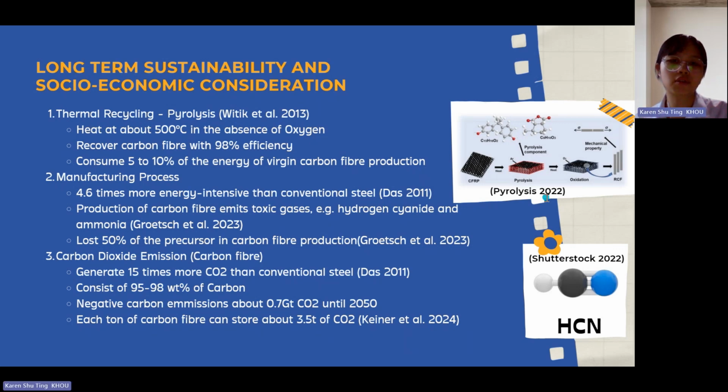First, in terms of long-term sustainability use, the material used should be recyclable. For your information, carbon fiber reinforced polymers are difficult to recycle due to their structure. It utilizes cross-linked thermoset polymers for their matrices. Here is one of the common methods of recycling, which is pyrolysis.